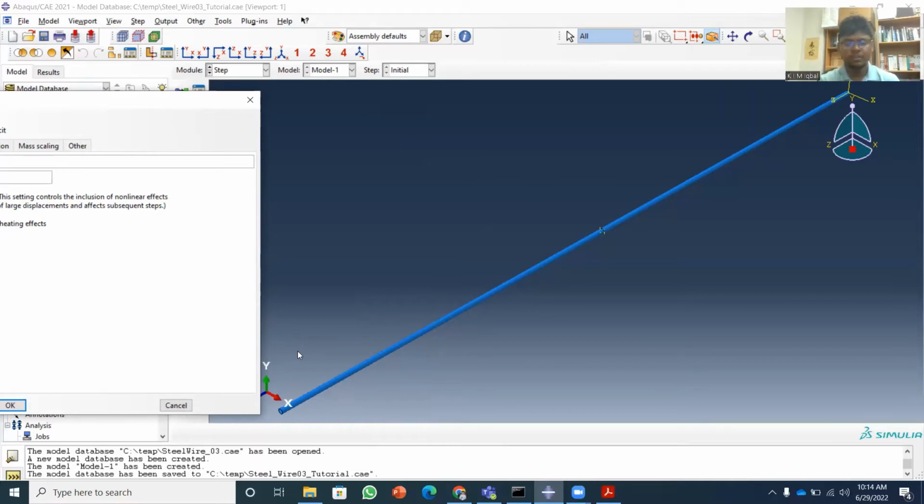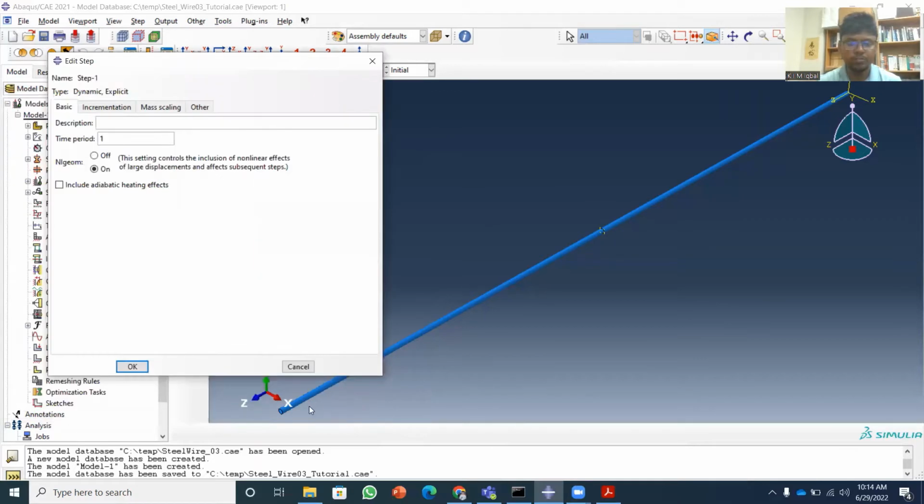There are a lot of equations available to calculate the speed of the wave in steel, or we generally know it's almost close to 5,000 meters per second. So you can get it this way. What I am going to do, I want to see another cycle. So instead of using 2D, I will use 4D, where D is the length of the pipe or the steel wire. By this way, if I calculate, that will be 0.00. You can calculate it by hand.